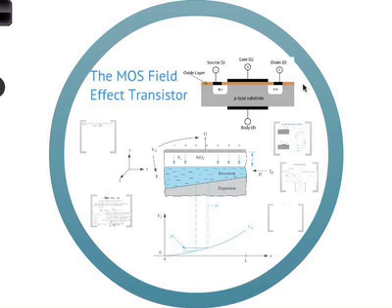Now, of course, the physical mechanism is that in the case of the p-type substrate, you apply a positive voltage, which, yes? I was just wondering, in the examples that we've been talking about, for the most part, have we been connecting the drain to the body? Yes. We have ignored the body so far because it's not so important. For everything we talked about so far, the drain and the substrate are basically connected, which means that this drain and this substrate has zero bias.